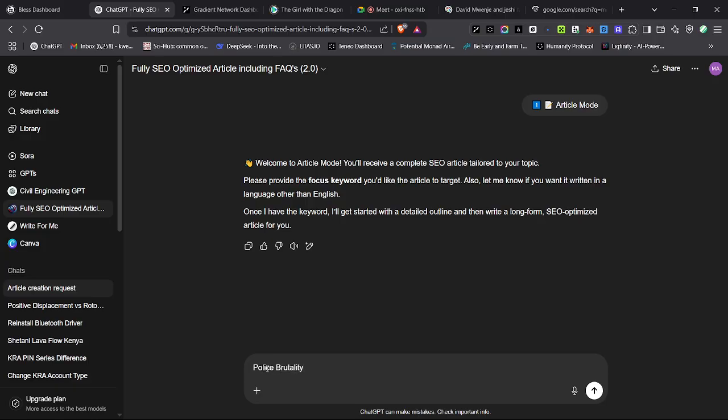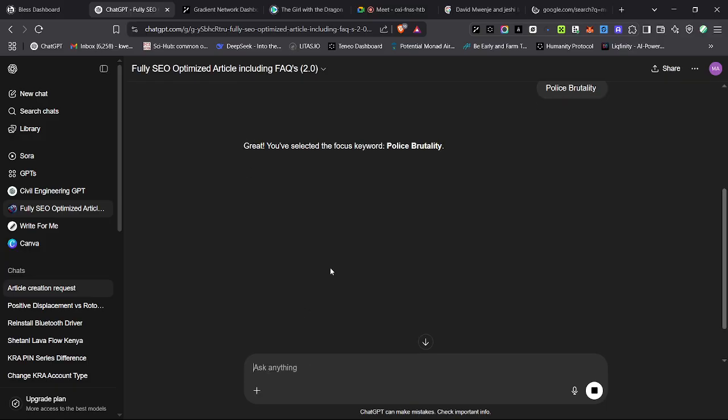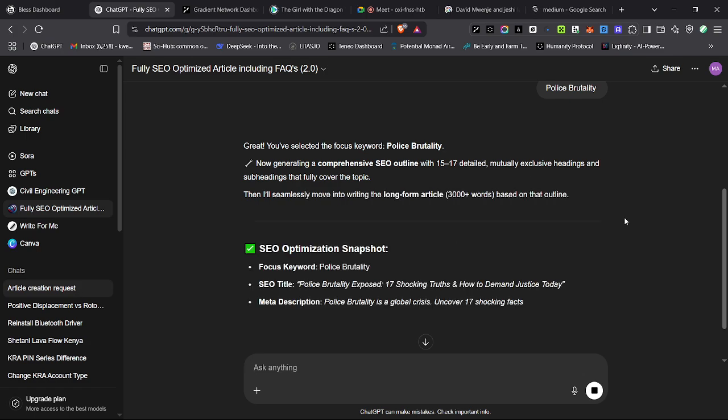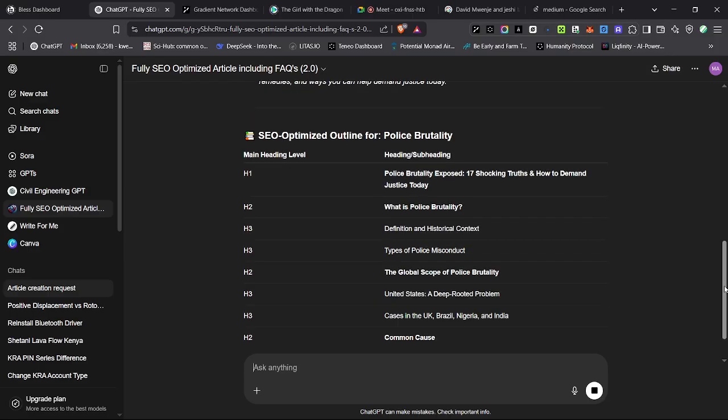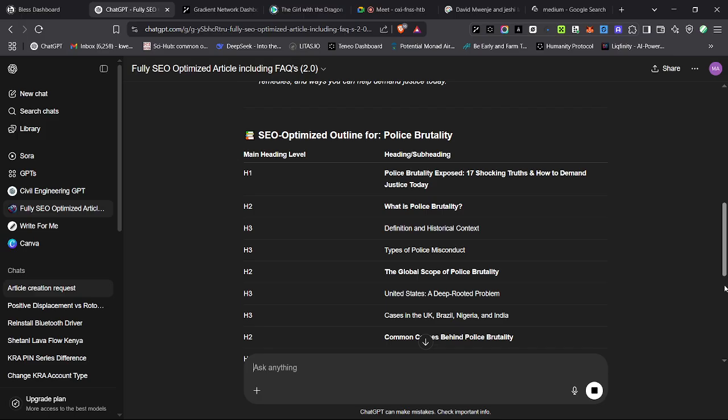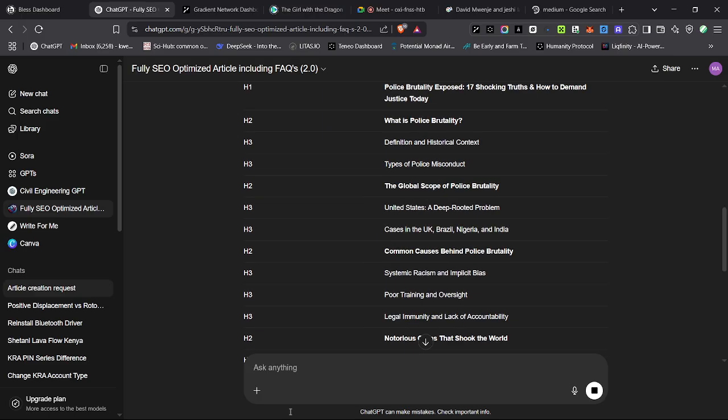Yes, KQ squared equals HF, which is equal to H by 3. You see that? The second derivative d squared P by dQ squared is always negative, showing that P has only one maximum value, not a minimum, with Q. So from H minus 3KQ squared equals 0, the maximum power is obtained when H over 3 of the head available at the source, that is the reservoir, is actually lost through friction when the flow is taking place in the pipeline.